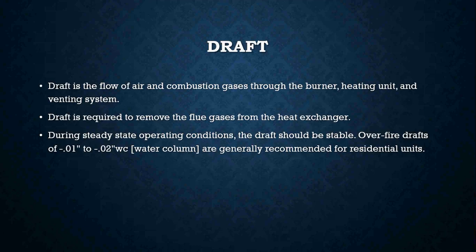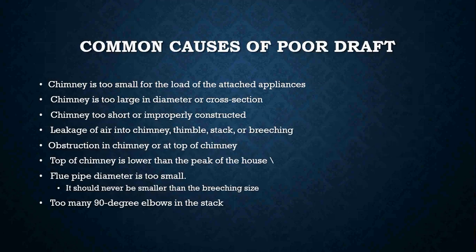Okay? Draft. Okay, is the flow of air and combustion gases through the burner, heating unit, and your venting system. Draft is required to remove the flue gases from the heat exchanger during steady state, which is, remember, after about 5-10 minutes of operation. Okay, the draft should be stable. Your over-the-fire draft should be negative 0.01 to negative 0.02 inches of water column. That's generally what we recommend on your residential units.